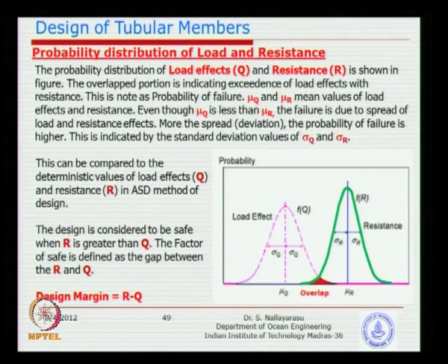Now if you look at this diagram, the load effect includes geometry, boundary conditions, and sections. None of them are going to change, because when we design a beam with a 10 meter span, tomorrow it is not going to become 11 meter. For sure it is going to be 10 meter every day. So what is going to change in the load effect is the load, which is the primary concern.